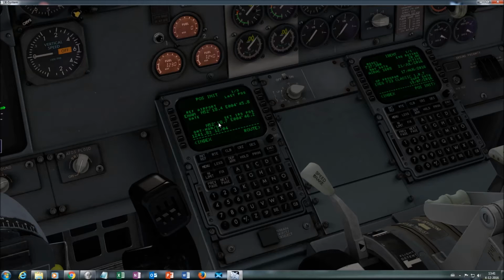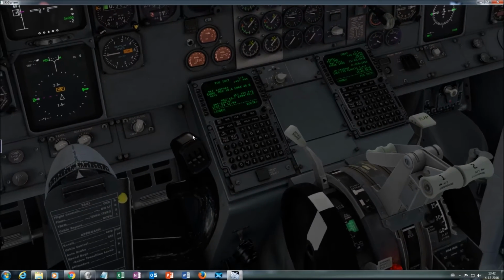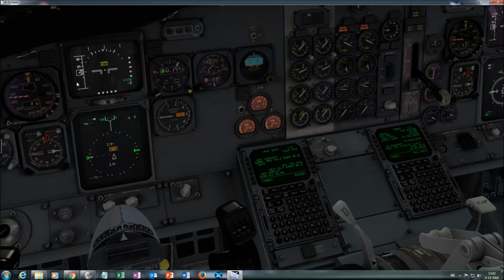of the FMC programming, it will affect the navigation, at least the lateral navigation of your entire flight. So this is a vital step. That's why I take so much time to explain it, for successful navigation. Well, we're done with that. So the POS init is now complete, and once the IRS is aligned, we see a normal PFD and a normal nav display.